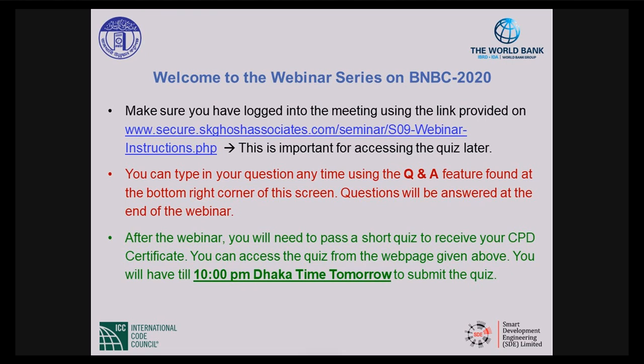Let me answer that. We have two choices. One, I don't have data. So what I have to do, I know the road. Normally in front of my road is either 1 in 30 years or 50 years. But I need 100 years. My life of a structure is 100 years that you want to design. Minimum 50 years return period, we have to use it. The major roads are normally in the 50 years, the big roads, and the inside roads are 30 years in general.